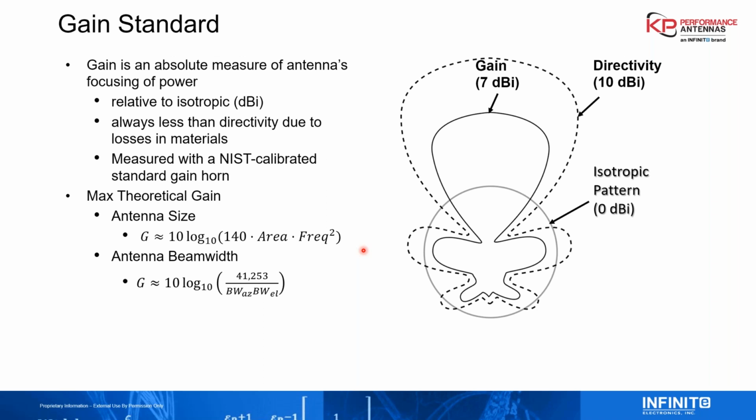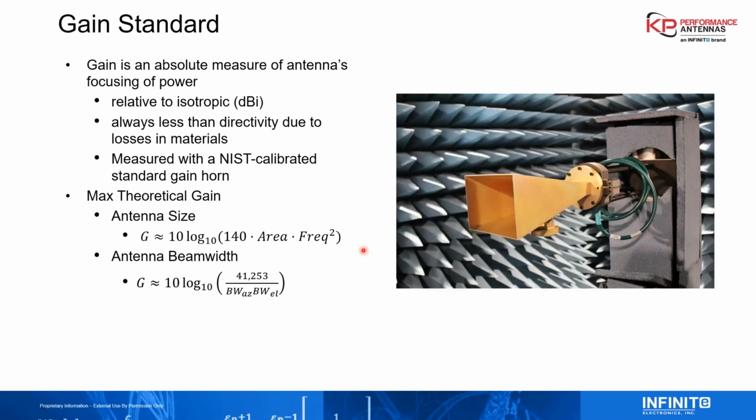It could also be an average gain or a typical gain, not a minimum gain. And typically gain doesn't stay one value across the band. It usually drops with frequency because the beam width ends up spreading in the elevation plane. But in any case, the definition is very important, and we just have some back of the hand calculations right here.